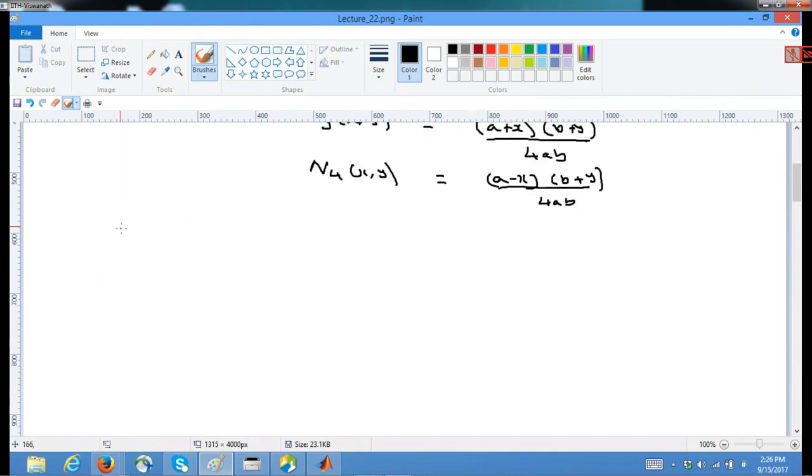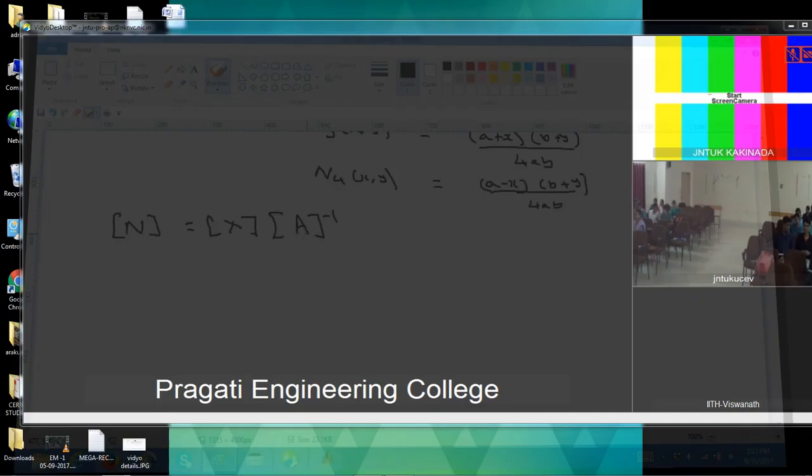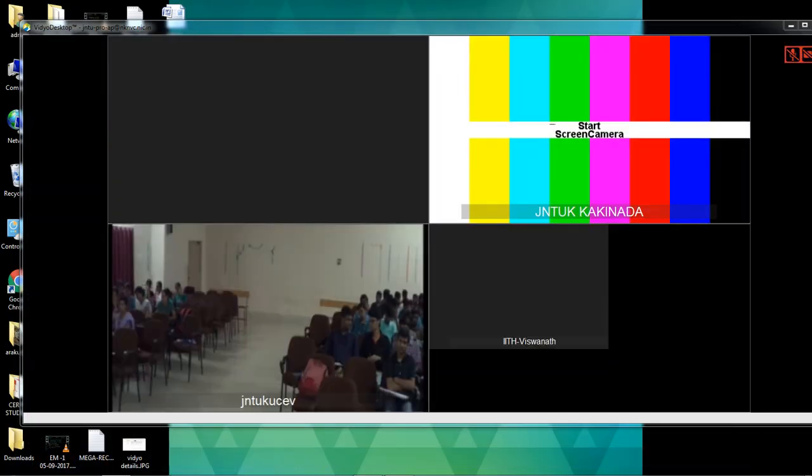for any generic element, the shape functions are obtained by choosing the basis function and evaluating this basis function at the nodal coordinates, and inverting it would get you this capital A, and A is the evaluation of the basis at the nodal coordinates, and then inverting it and multiplying with the basis vector will give you the shape functions.